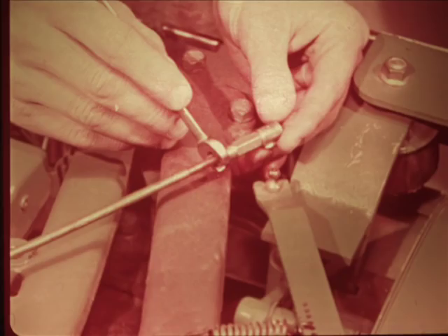Be sure to also check the governor-to-throttle linkage rod adjustment if the governor does not respond to load changes. With the engine stopped and tension on the governor spring, the stop on the carburetor throttle lever should just touch the stop screw. If an adjustment is needed, just lengthen or shorten the rod at the ball joint.